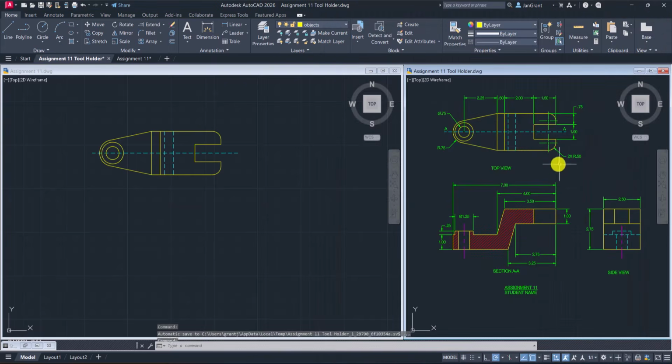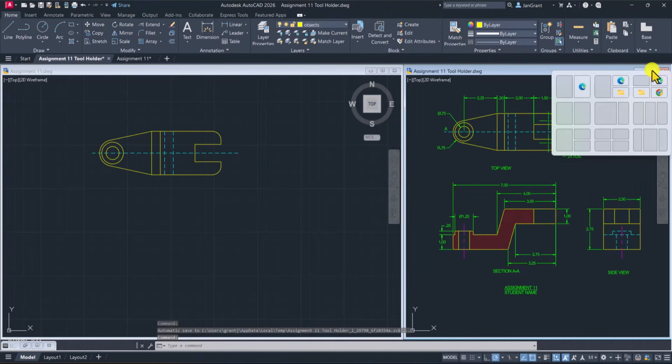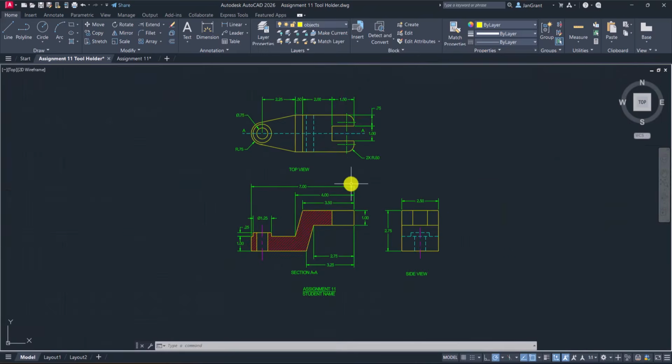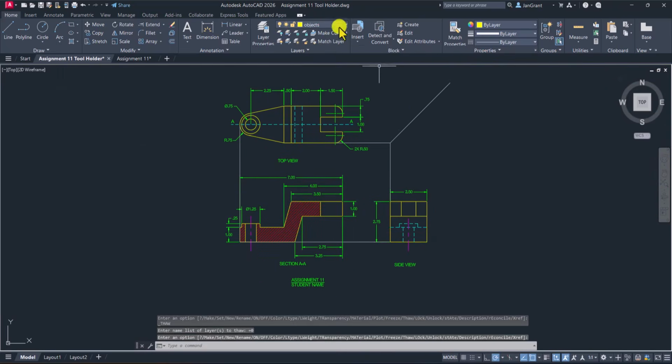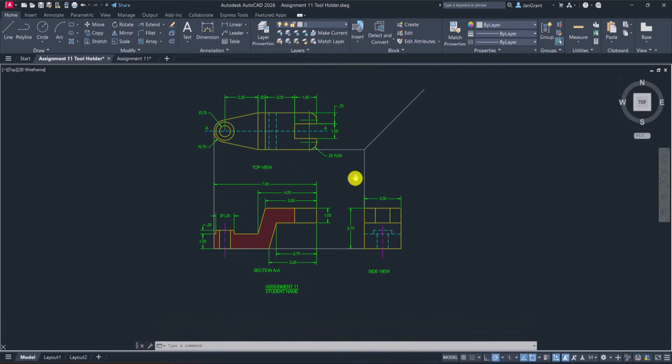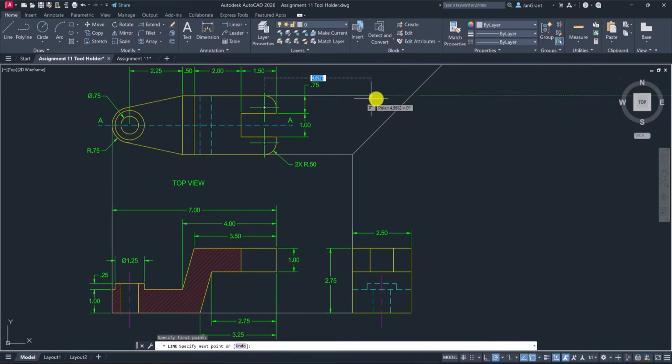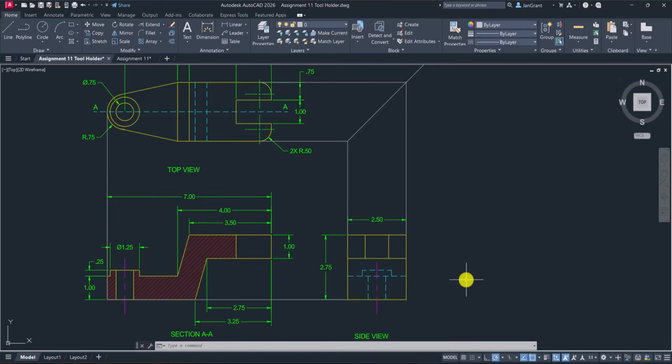So going back to our drawing, before we draw the side view, I want to use this drawing to show you where those lines are coming from. Just as a reference, this bottom line of the top view is going to come over, and then it's going to come down to create the beginning of the side view. From this intersection, we draw a 45-degree line. Then from that, we can pick up any one of these lines from the top view to project down to the side view and find our side view line work.